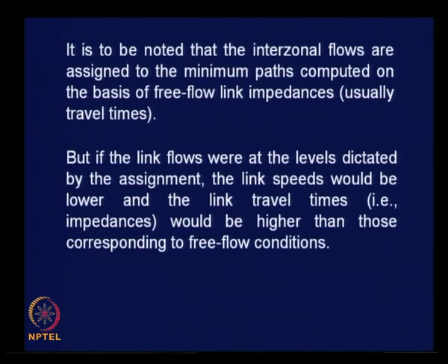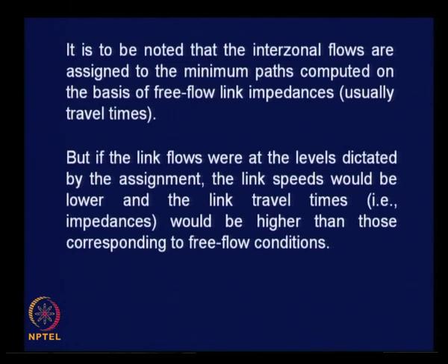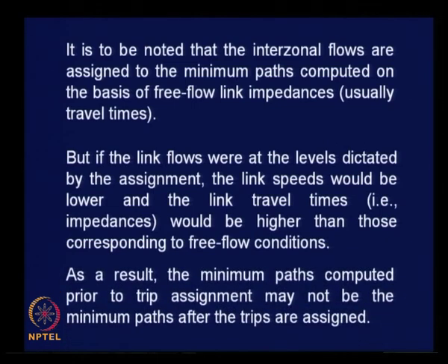This implies that travel times in practice may not be equal to the free flow travel time that we normally consider for assignment under all or nothing assignment technique or multipath assignment technique. As a result, the minimum paths computed prior to trip assignment may not be the minimum paths after the trips are assigned.